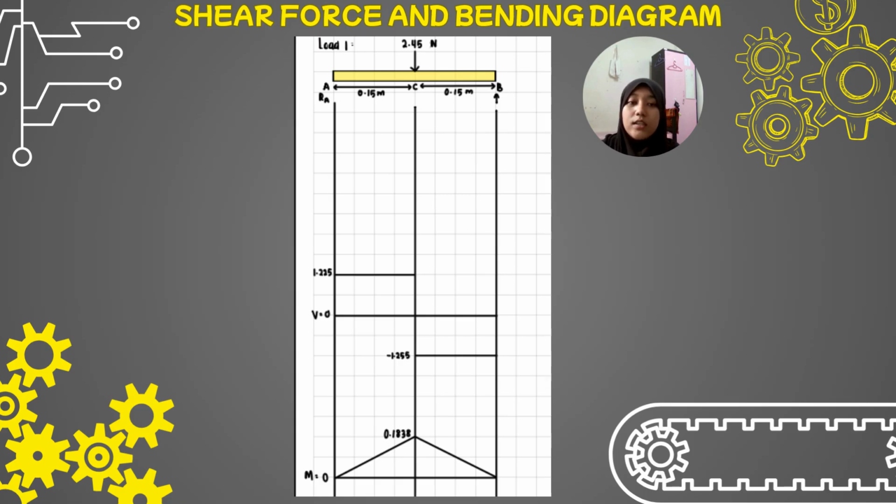At the center, a downward force is applied, calculated by multiplying mass by gravity, which is F equals mg. Because the load is perfectly in the middle, the upward support reactions, Ra and Rb, split the load exactly in half. Below each beam, we have drawn two key engineering charts: the shear force diagram and the bending moment diagram.